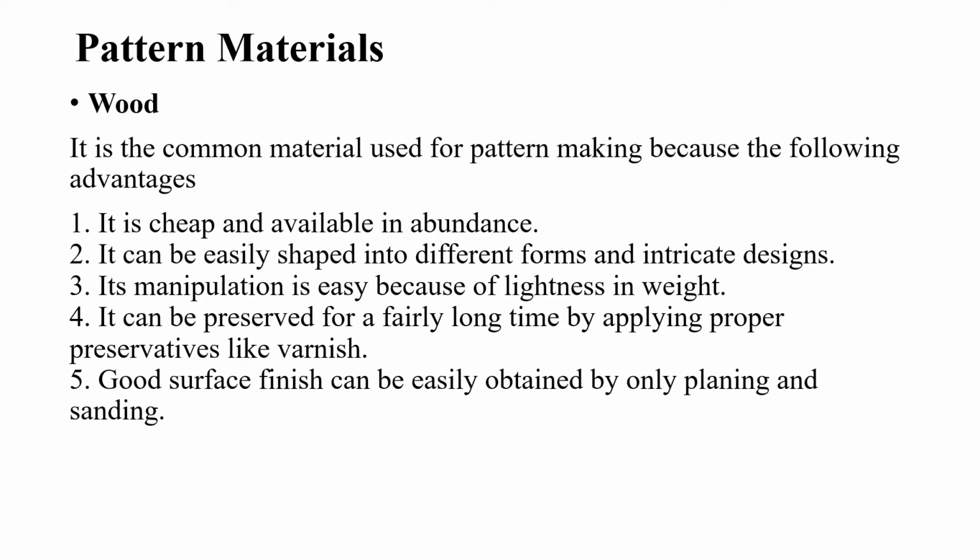or in that pattern. So the pattern material, or the material that you may use to make the patterns: we may use wood, which is very cheap and available everywhere, and it is easy to make the required design or shape. Wood is light in weight, so it can be preserved and used many times.